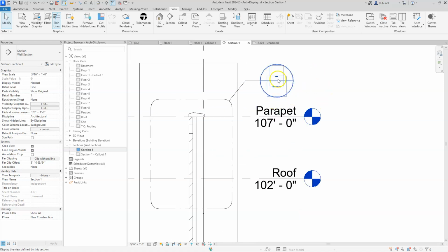If you've been wondering why we don't have numbers populated in this view bubble, just remember that those don't happen until this view that we just created gets dragged onto a sheet. As soon as it's dragged onto a sheet, it'll give it a detail number, and it'll align the sheet number with the sheet that we put it on. So fairly straightforward, not too tough.